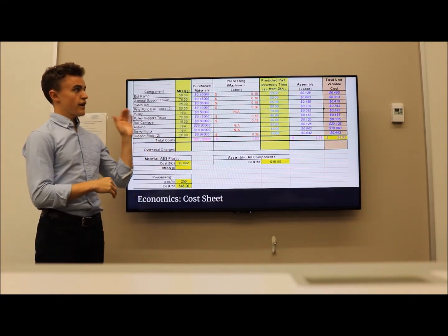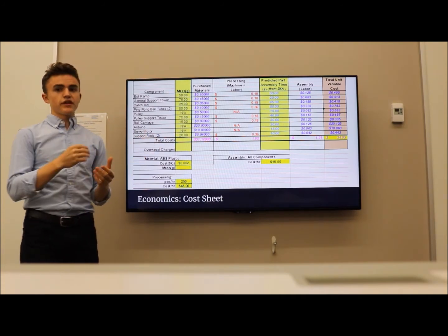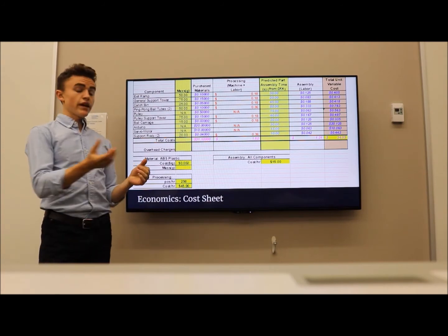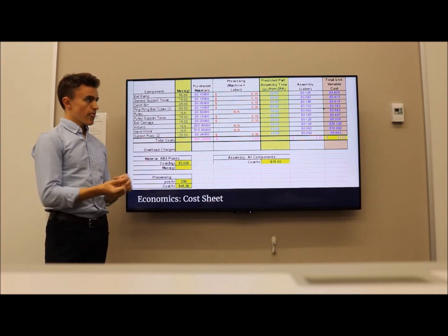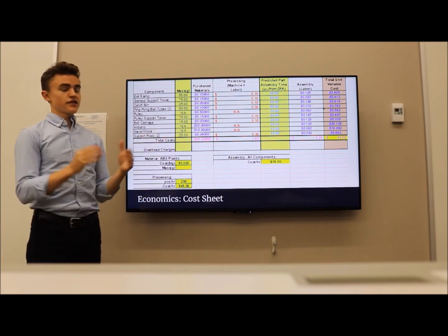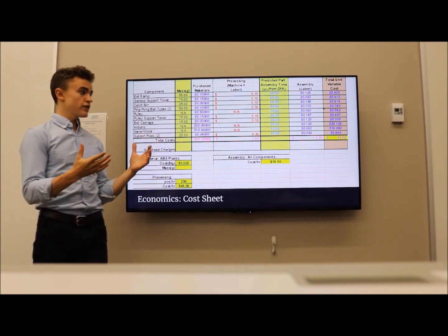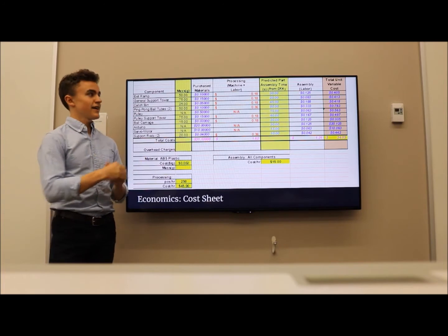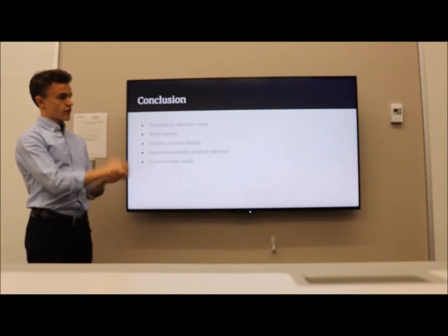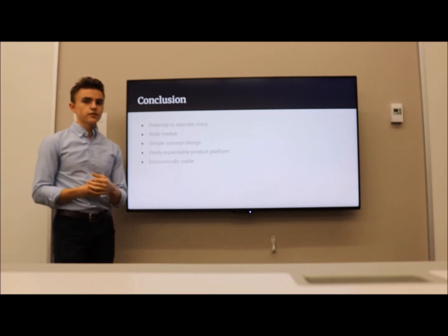We also have a machining cost, and that's based on an hourly cost of $45 to machine each component, and a rate of 250 pieces per hour. Third and final component of the total unit variable cost is the assembly cost. This is essentially a labor cost based on a wage rate of $15 per hour and assembly times that are calculated in our DFA.